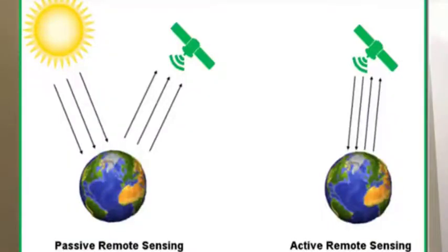Now with remote sensing, there are two kinds of systems which we can see here. There is a passive system and an active system. In a passive system, we use natural radiation or sunlight as the transmitter, and we use the pulses and energy from the sunlight off of the target and acquire that data through our receiver and analyze the data in post-processing. In an active remote sensing system, we use our system to actively send and transmit laser waves or other forms of radiation towards our target, and we use that same system to analyze and receive the data.